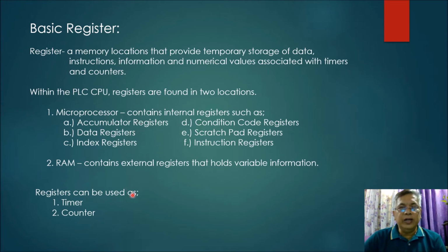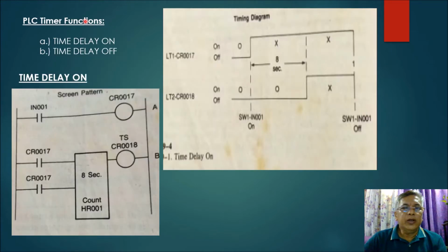Okay, so as I've said earlier, registers can be used as a timer or as a counter. Okay, so we go now to register used as a timer. Now there are two basic PLC timer functions, one of which is your time delay on and the other one is your time delay off.